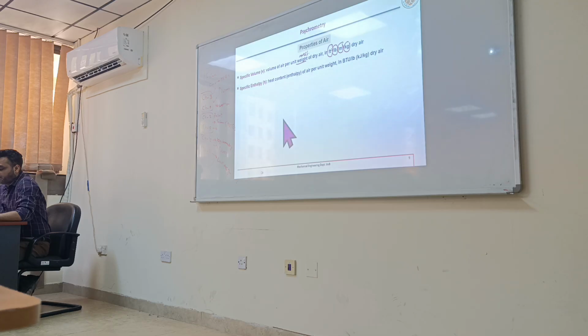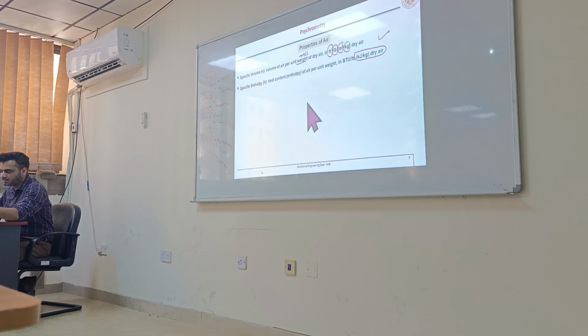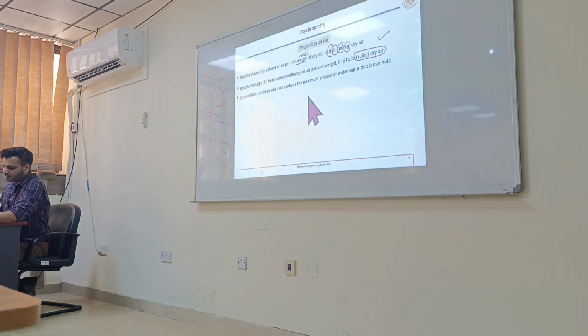Then enthalpy, that is a very important term. Enthalpy of this air per unit mass of dry air. Okay, let's discuss this in more detail. Specific enthalpy, h, enthalpy of air per unit mass of dry air. And what is enthalpy? Enthalpy is energy content, U plus PV.